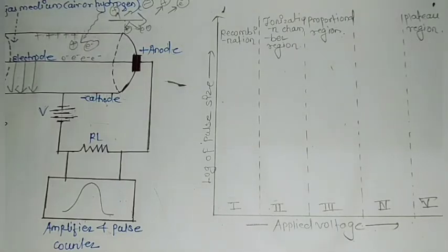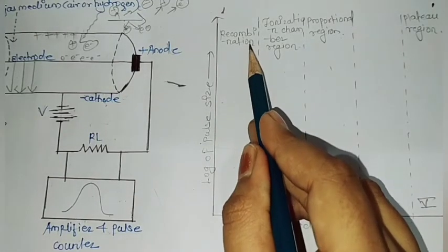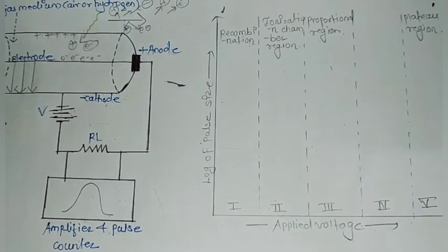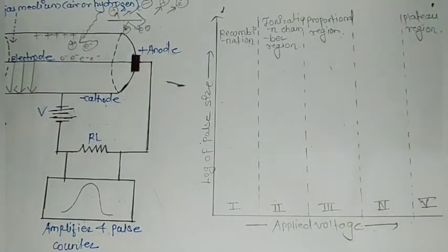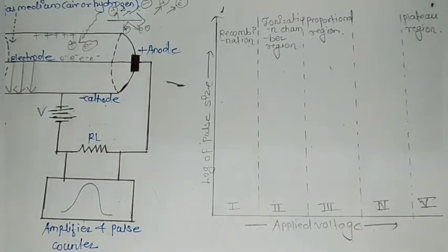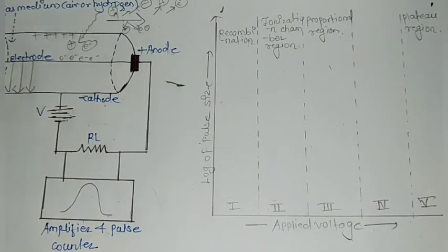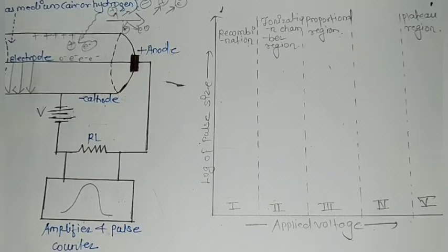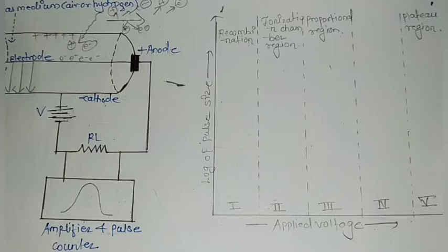This process is known as recombination. So recombination is a process in which the ions created by the ionization due to some external particle, due to the thermal motion, come back together and recombine to form neutral atoms. Once they have become neutral atoms, they are useless and do not contribute towards the current in the load resistance at all.